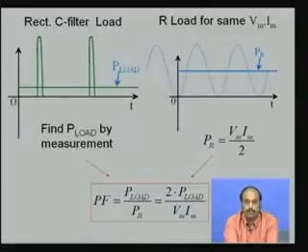In fact, you have to pay more if you are having low power factor loads, and if you are having unity power factor loads, which means close to resistive load, then you are optimally utilizing the mains or the grid, and therefore you will be less penalized.